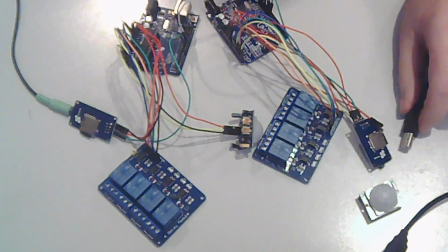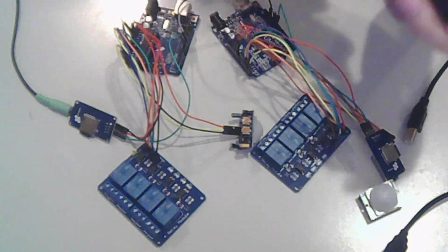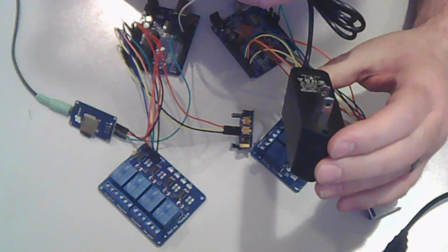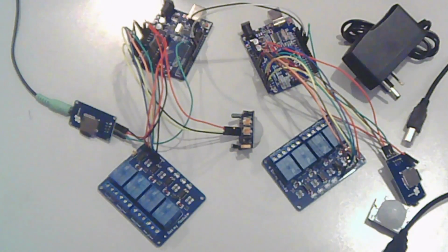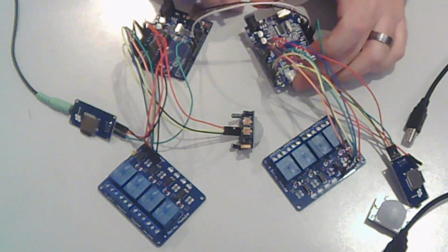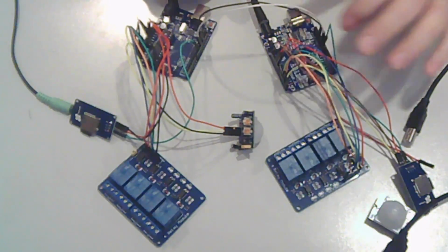And I'm going to need a secondary power for this other Arduino, just to make sure. A center positive running at 9 volts DC. Okay, so a quick Google search reveals that 9 volt is acceptable. The upper limit for the Arduino R3 is around 12 volts, so 9 volt is ideal actually. And hope we don't blow up the world here.